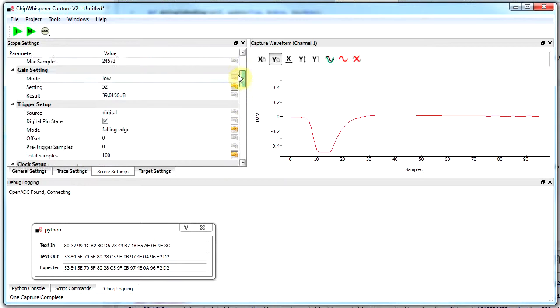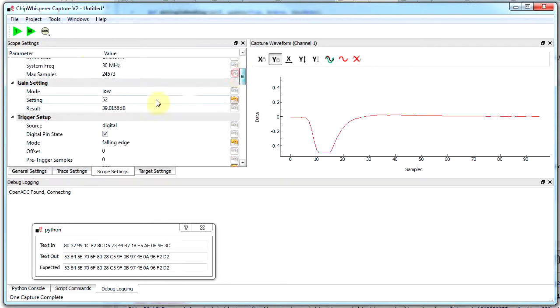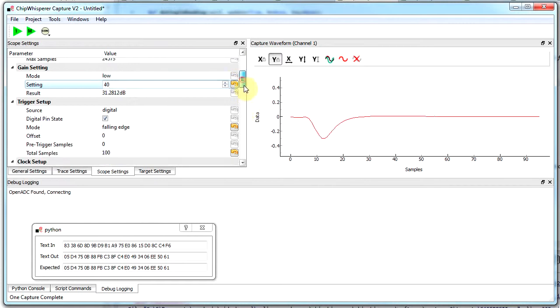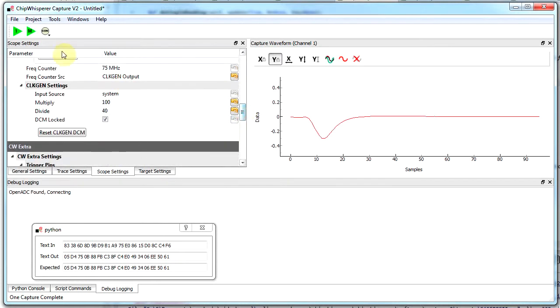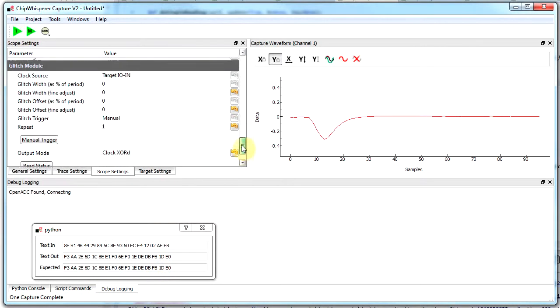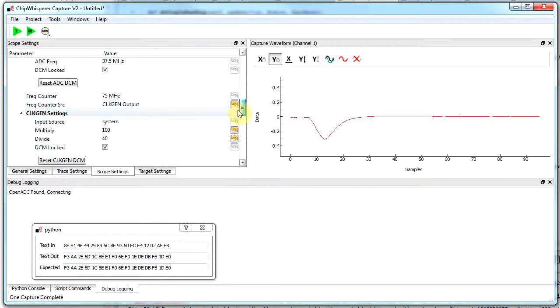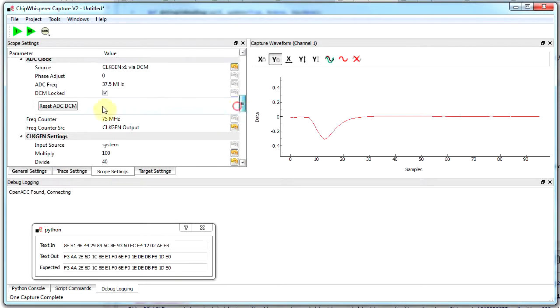So this is cool because now, if you want to investigate things like the varying clock countermeasure, you can look at, well, what is the response of the system in the presence of a varying clock? And the ChipWhisperer helps you script that whole thing because you can generate a new clock frequency, take a measurement, generate a different clock frequency, take a measurement, or take a bunch of measurements under one clock frequency.